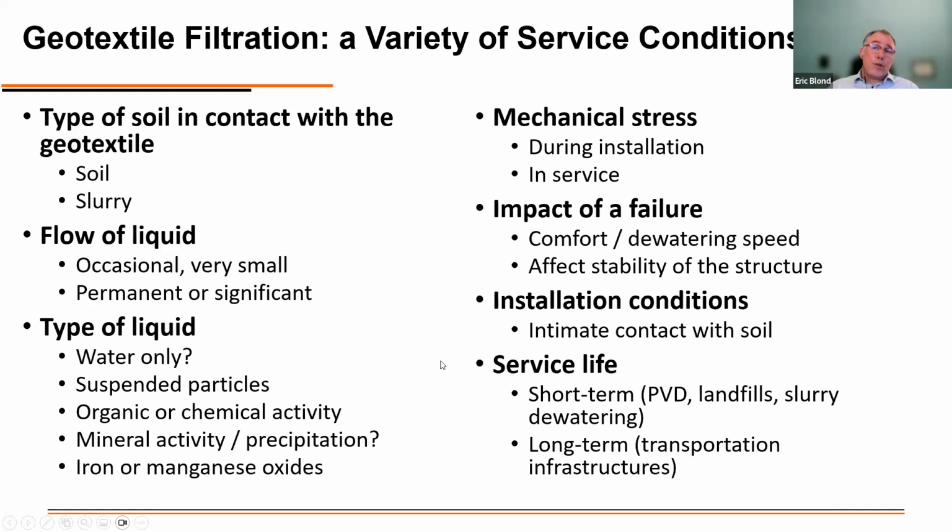And after that, service life. What do we expect in terms of service life? As I said before, PVDs, we typically expect a couple of years of a service life. Landfills, I consider a couple of years as well for the base of a landfill. For the capping, it's a different story. But for the base, for the primary drainage layer, it's essentially the short duration during which we are filling the landfill.